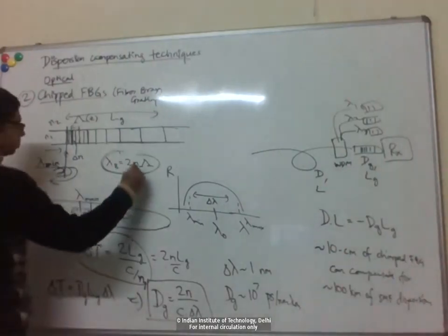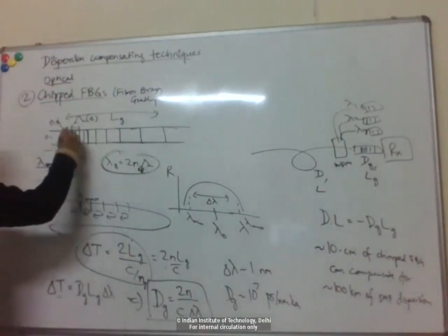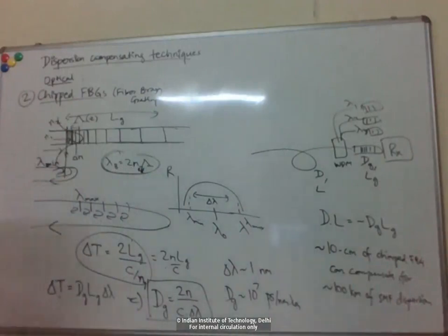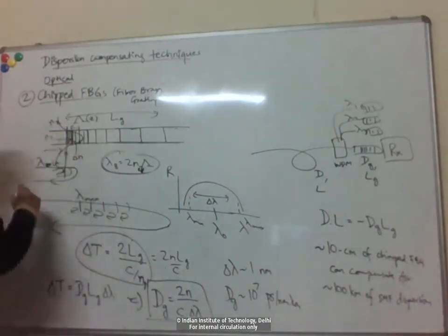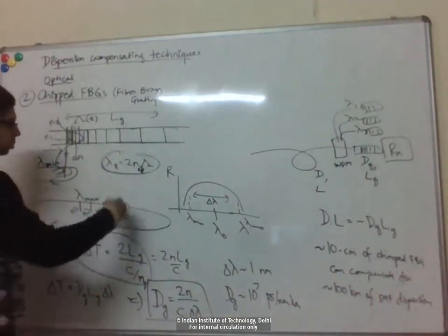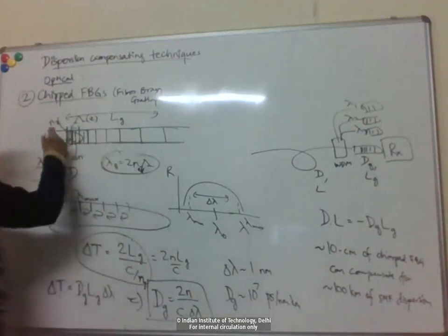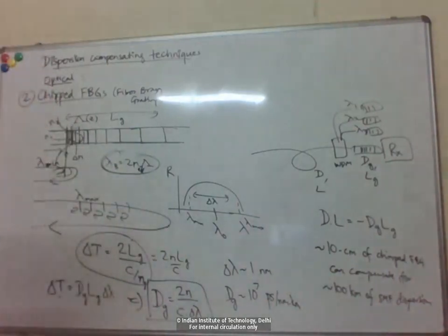Right, so you have some mode here which is incident. And again, N1 and N2 are very close for single mode fibers, and N effective lies between N1 and N2. So for all N here, you can use either the core index or the cladding index. It doesn't make much difference.